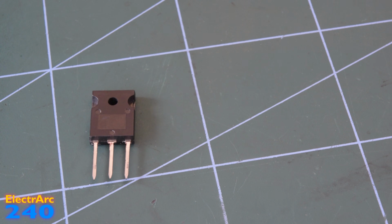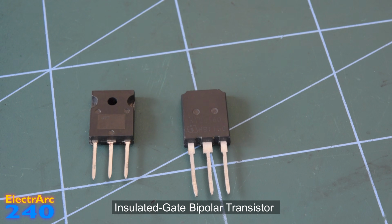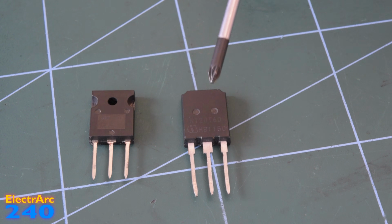And actually, finally, to finish off, we're going to take a look at two devices that are very similar to MOSFETs, but technically aren't MOSFETs. The first is the IGBT, which stands for Insulated Gate Bipolar Transistor. Now the gate part is almost exactly the same as a MOSFET. We can drive it in the same way, we even drive it with the same chips. But the difference is in what the gate is doing. In an IGBT, the drain and the source are replaced by the collector and the emitter, and the channel is replaced with a junction. IGBTs are more similar to silicon carbide MOSFETs than standard silicon MOSFETs, at least in terms of the voltage they can operate.